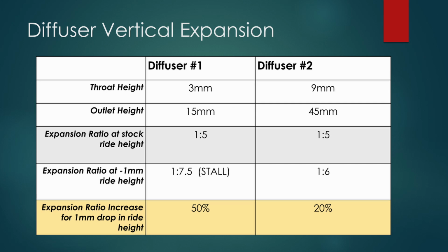And you can see from this why you have the effect of porpoising in F1, because they have a limit to the size that their diffuser can be, so they're going to try to push that throat height as close to the ground as possible, which means the diffuser is closer and closer to that state where it's potential for it to stall, to be able to maximize the performance of the diffuser.